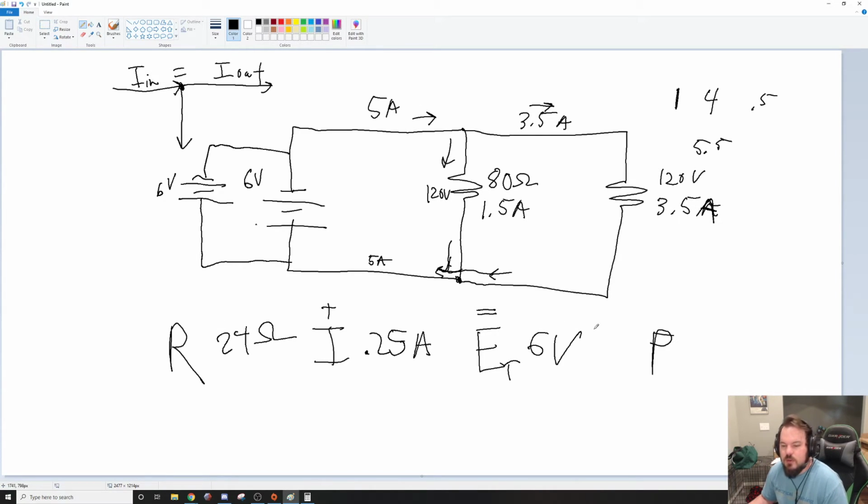So, oh, and power in parallel adds up. So all the different individual powers always add up. So your current is 0.25 amps. The multiple voltages in parallel didn't matter as far as calculating everything. What you're getting out of adding another battery in parallel is runtime. So this circuit will be able to run for twice as long with 2 batteries in parallel.